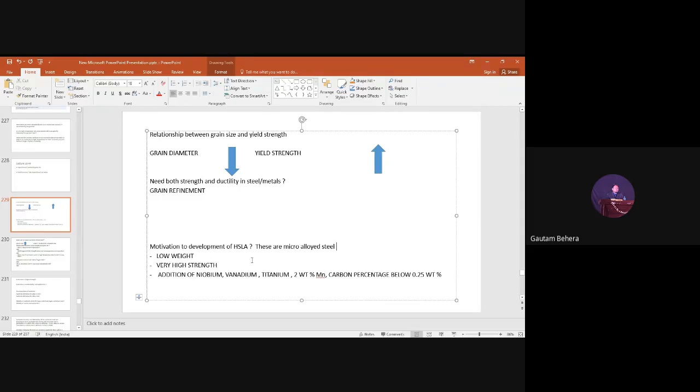They do not allow the austenite grain to grow bigger and bigger at such a high temperature, 1000 to 1050 degrees centigrade. In other words, they provide strengthening by precipitation and along the grain boundaries, and they prevent grain coarsening. They keep the grain smaller in size, which is grain boundary strengthening. If we have a smaller grain, there are more obstacles to dislocation motion. So you understand the relationship between austenite grain size and strength in high strength low alloy steels.